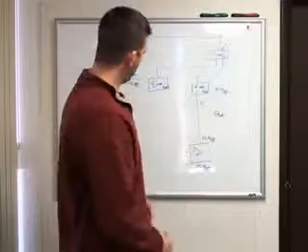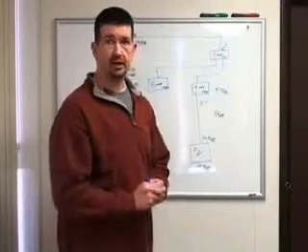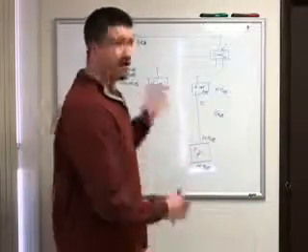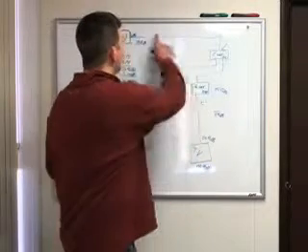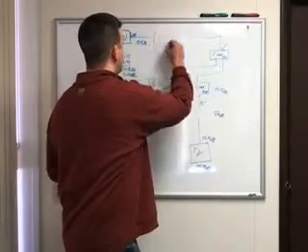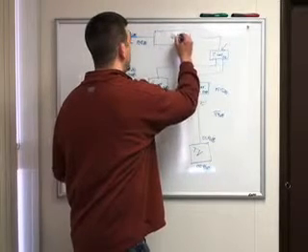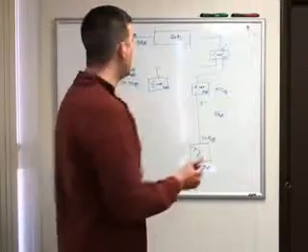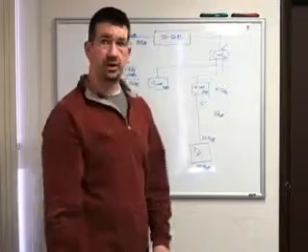So for example, if wherever one of these TVs was at, somebody was putting a second TV or something that required a second signal, we have a little bit of room to move on the amplifier. So we're going to put a 30 dB amplifier in here with again, it has 10 dB gain adjustment, so this can technically be adjusted anywhere from 20 to 30 dB.